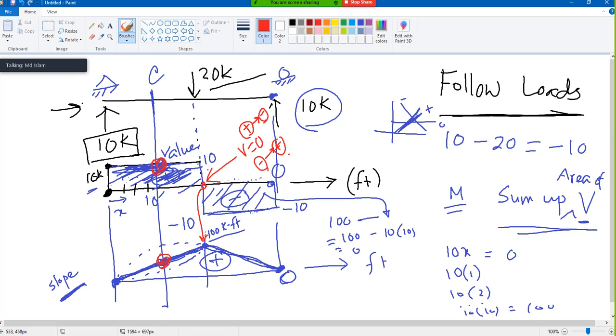So this is a very important statement. Where shear force is zero, there is a very good chance moment is maximum at that point. Now you can see my shear force is zero here also, zero here also, but it is not maximum here. It's not that everywhere it will be maximum, at any of these 3 points where shear force is zero. But if you know where the sign is changing, that is the critical point. Where shear force changes sign, moment is maximum at that point.